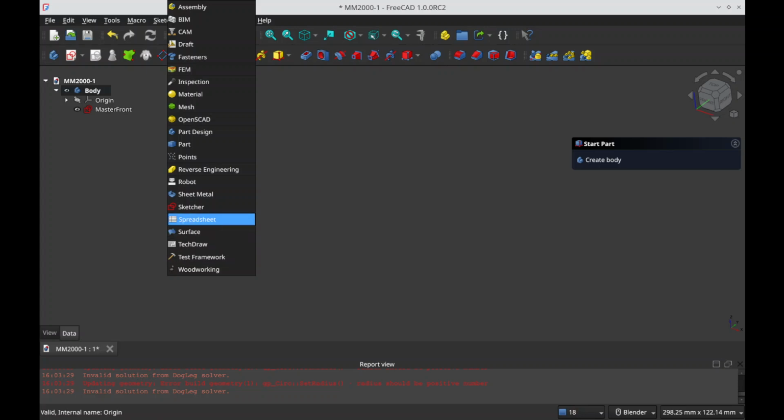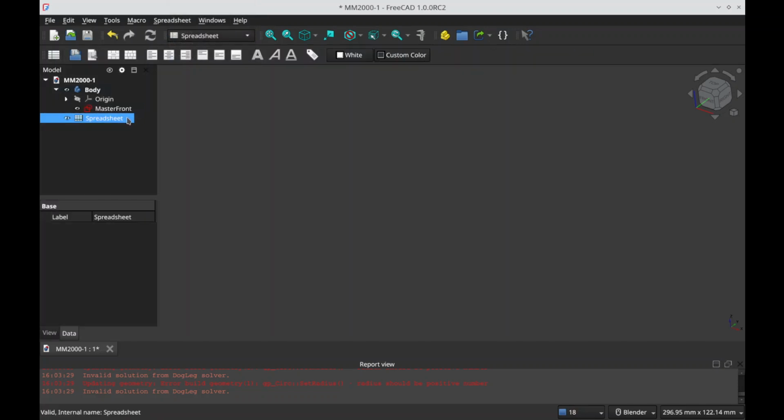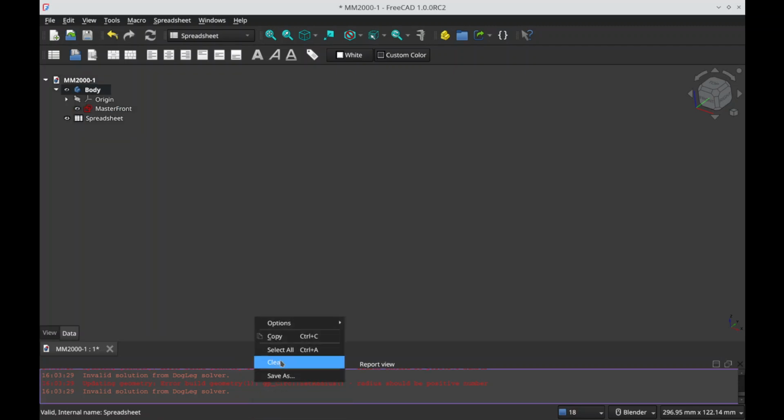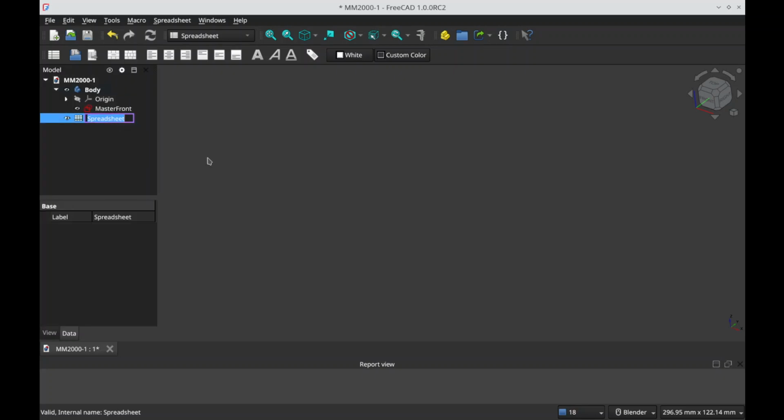Before I get into that, I wanted to create a spreadsheet. And the spreadsheet is just going to have our dimensions because we're going to have certain things referenced in multiple places. It's probably not absolutely necessary, but it's reasonably good design practice. So let me clear off some stuff here. I name my spreadsheets D so I can refer to them quickly.